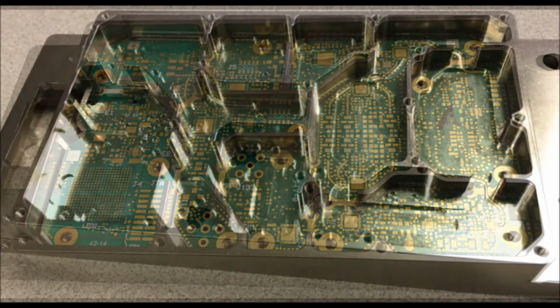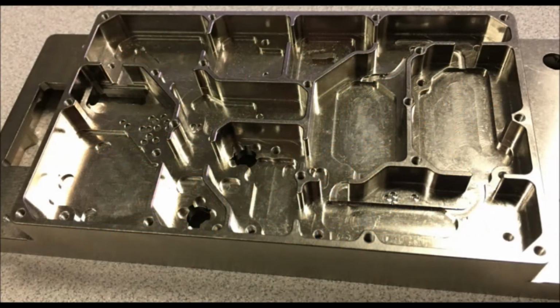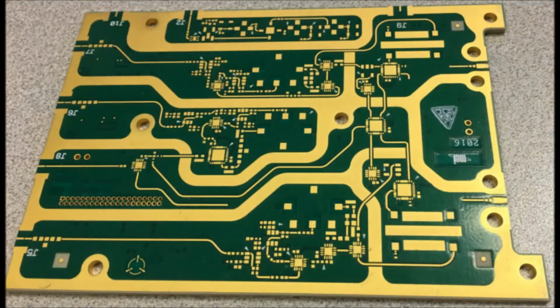Here's a picture of just the chassis by itself. You can see the pockets that have been milled into the metal to provide clearance for the board and the components and conductors on the bottom side of the board. And here's an image of a board that will have a shield chassis part mounted on top of it. The chassis will not go through the board. This kind of shield has an EMI gasket material dispensed in paste form into channels in the bottom of the shield walls that hardens somewhat to provide a permanent seal.